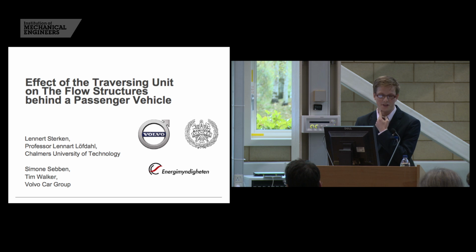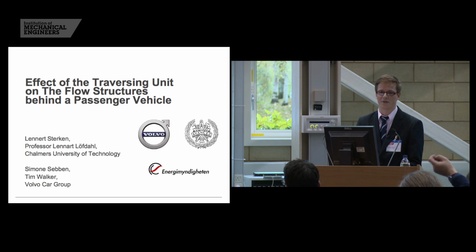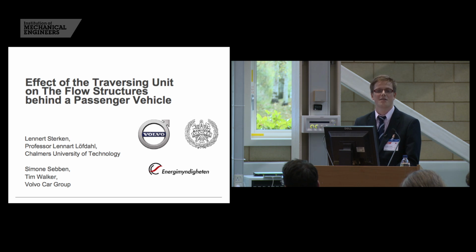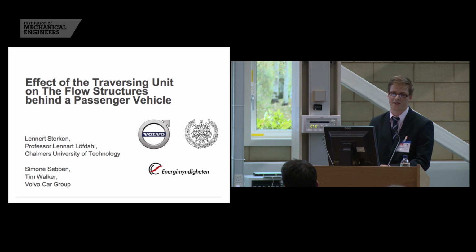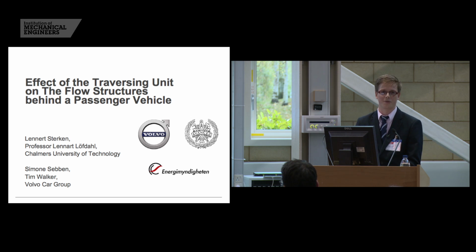The test had to do with making wake measurements because I was interested in the wake flow behind the car. The wind tunnel engineer asked me if I wanted to also save the forces measured by the balance of the car, which at that moment wasn't done. I was a bit surprised by the question because it was my first test, so a little bit unknowingly, I said yes, of course. I'm interested in the balance forces as well while conducting these wake measurements. Looking at them later, it showed that there were some variations in my balance forces, and this kicked off this paper.